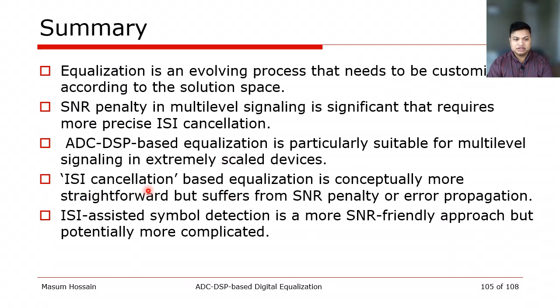ISI cancellation in general is easier to understand and implement, but it has an SNR penalty. Therefore, ISI assisted detection technique is more suitable from an SNR point of view, but its complexity must be reduced, and that's where the future of equalization is progressing.